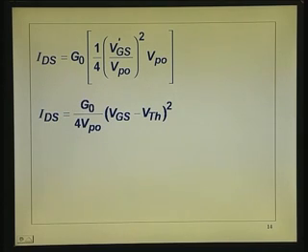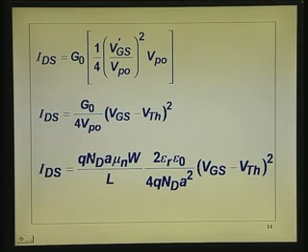So I_DS is therefore, expanding that, G naught by 4 V_P0, I have got V_P0 pulled out from there, that is V_P0, 4 is pulled out, times (V_GS minus V_T) whole square. Now it is even more pleasant. So it looks like our familiar equation for the MOSFET. What is this quantity? Expand that. G naught we write, it is channel conductance, which is actually q N_D mu sigma A by L, sigma is that quantity, area W into A by L, that is G naught.